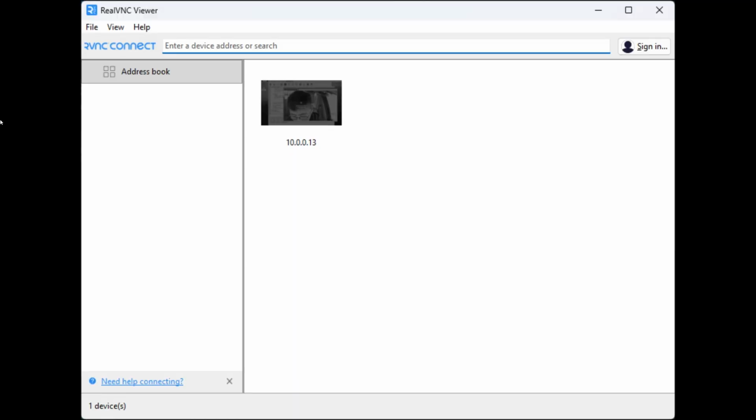After training my YOLO model on my computer, the next step was getting it to run on a Raspberry Pi. This required remote access, model conversion, and optimization for a low-power device. I used VNC Viewer to remotely access the Raspberry Pi's desktop from my computer. This allowed me to see the Raspberry Pi's screen, run Python scripts, and debug problems without connecting a separate monitor, keyboard, or mouse. VNC Viewer basically lets my laptop control the Raspberry Pi as if I was using it directly.